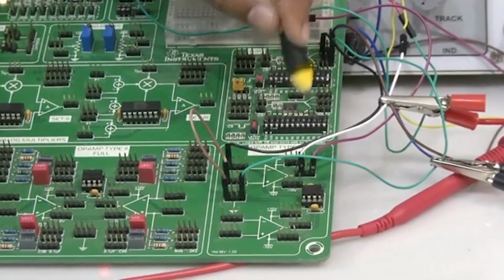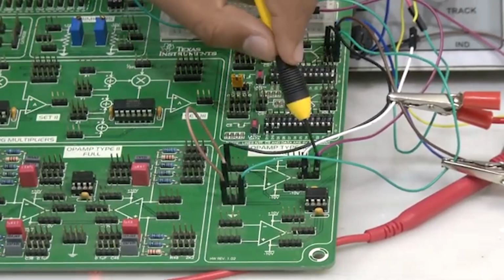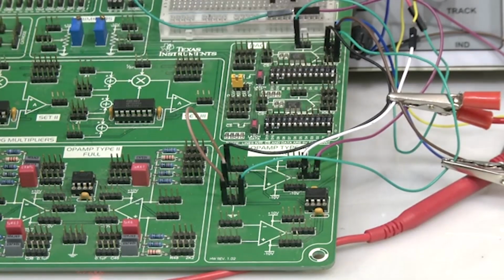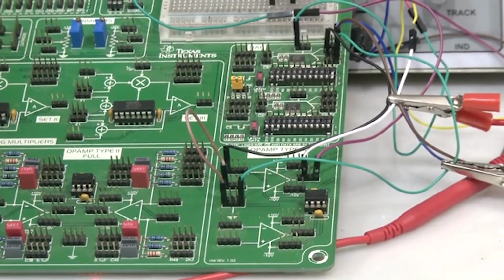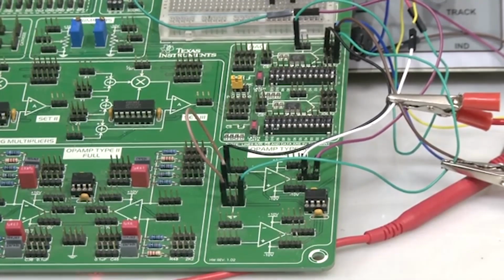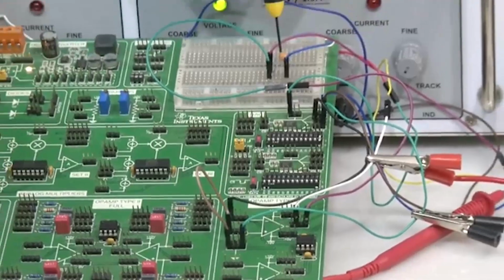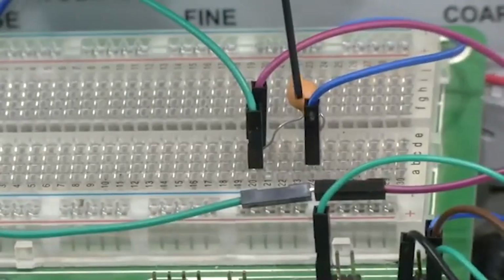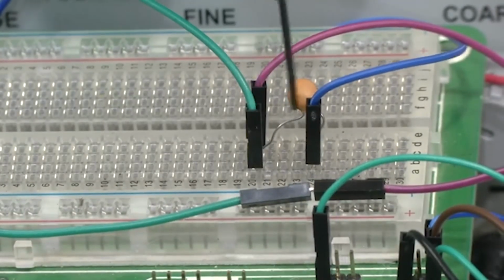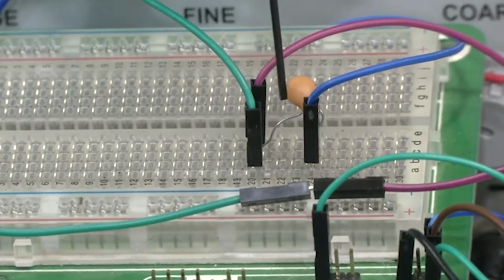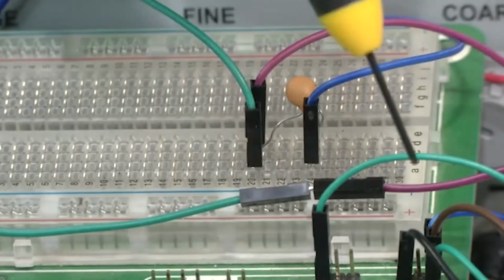And as per our circuit design we have also connected a capacitor between the feedback line and the inverting input. If you have to add an extra component, we have to use the breadboard that is provided, we have seen that. So, we have added this capacitor, this yellow color component, between the feedback line and the inverting input terminal, for avoiding gain peak. Now, we are all set to see the connections.